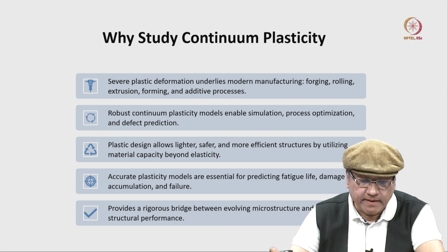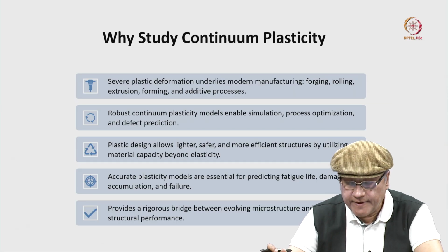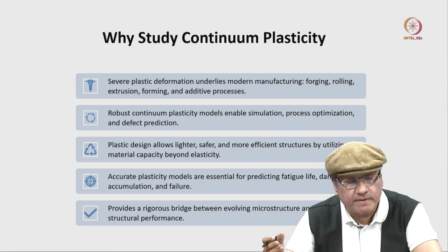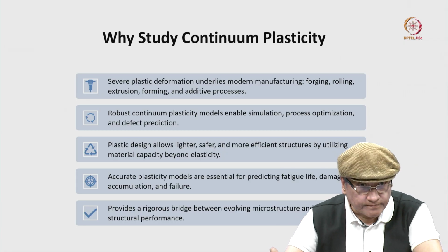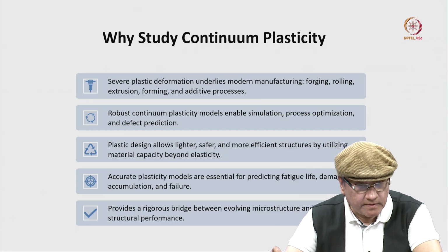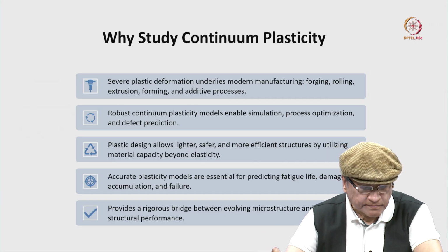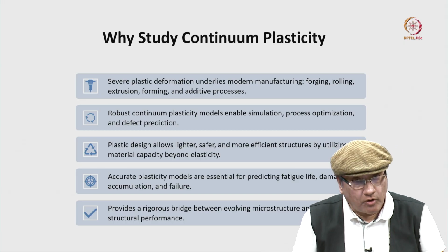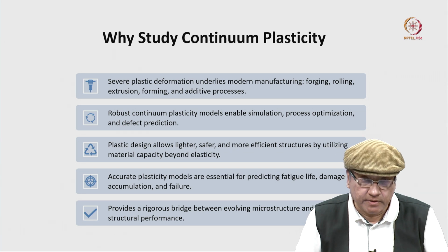Also, plastic design allows for lighter, safer and more efficient structures, because it utilizes material capacity beyond elasticity. So you have less factor of safety incorporated automatically in your design. And accurate plasticity models are essential for also predicting the fatigue life of components and damage accumulation and also failure.